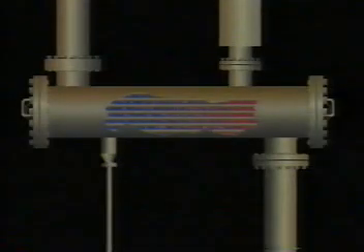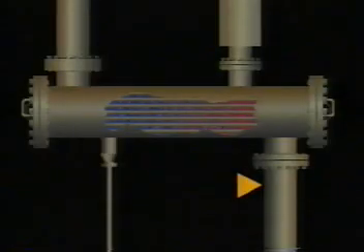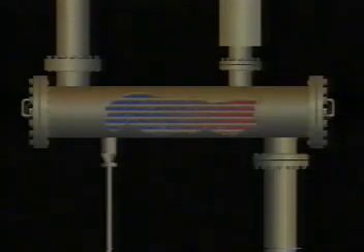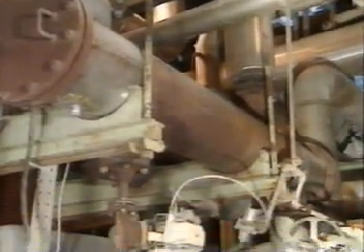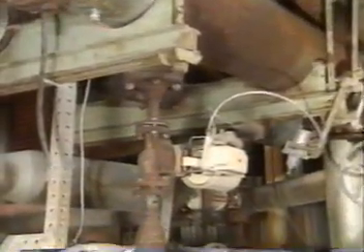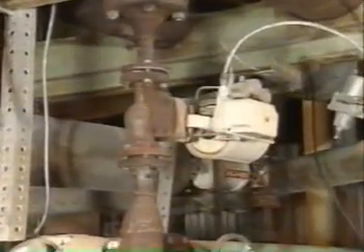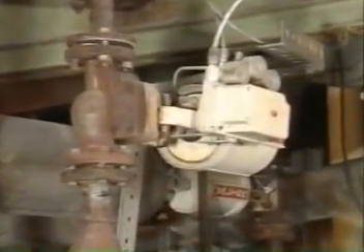In the heat exchanger shell, the steam gives up its heat to increase the temperature of the second fluid, which flows through the tubes. The fluid to be heated by the process enters the heat exchanger here and passes through the tubes. After being heated in the tubes, it flows out of the heat exchanger. In this example, the temperature of the hot fluid leaving the heat exchanger is measured by a sensor. The control system controls the temperature by positioning this valve, which regulates the flow of the working fluid leaving the heat exchanger.